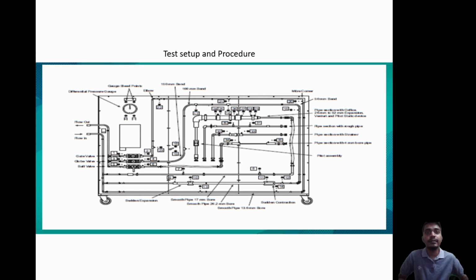The computer's Darcy Lab was connected to the DAQ system and the flow rate meter. The flow rate meter was used to automatically calculate the volume flow rate. When there is running water, the Darcy Lab provides the input and output signals. The water pressure was controlled by adjusting the control valve. All readings and outcomes were documented and tallied.